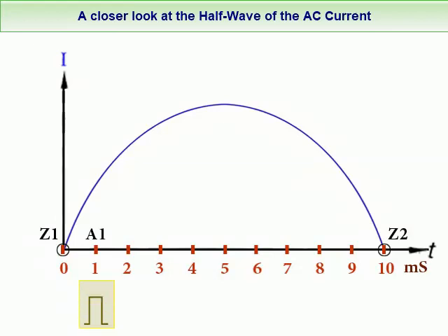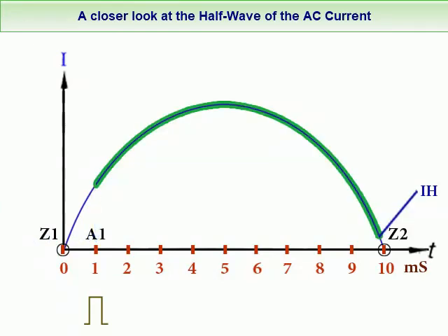As the microcontroller triggers the TRIAC at point A1 just once, by sending the 1 for 225 microseconds followed by 0, the TRIAC switches on and enters the on state, during which it remains conductive despite the absence of the triggering signal. Of course, the device is connected to the electrical supply immediately when the TRIAC is triggered, that is at point A1. The current flows in the device from point A1, until it reaches the value of the holding current IH that is close to 0, where the TRIAC enters the off state, and of course, switches off due to the absence of the triggering signal.